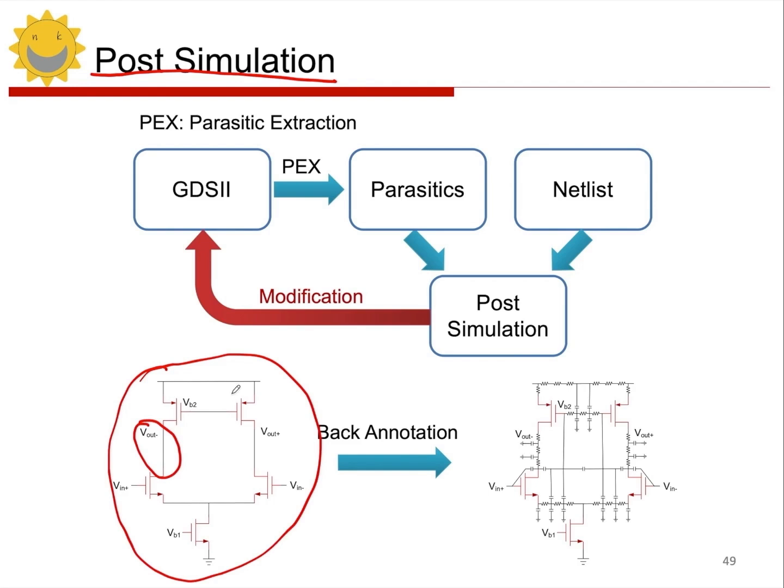However, once we finish drawing the layout, the metal lines are definitely made up of different layers of metal. When we introduced the cross-section of the chip earlier, we could see that there are parasitics between these metal lines. So once parasitics are present, the actual situation might look something like this, illustrative. It not only has parasitic capacitance, but also parasitic resistance, right?